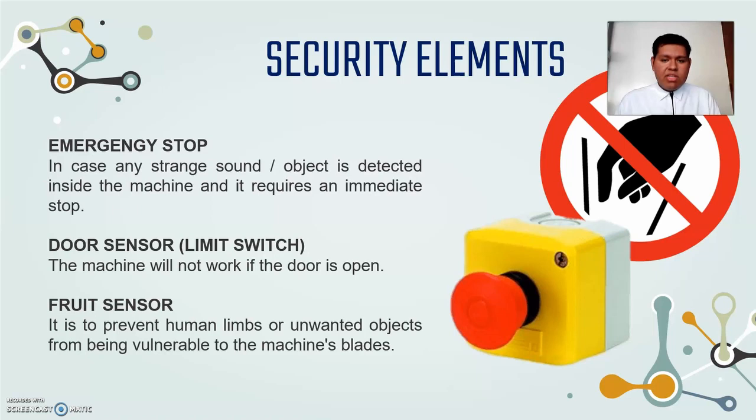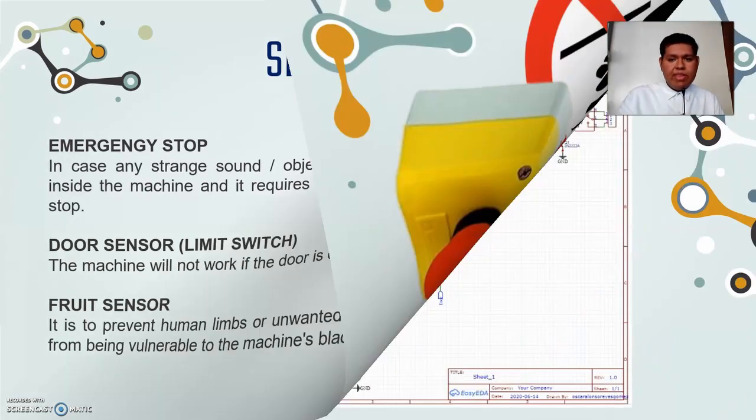Next we have the door sensor, that tells us when the door is on or not, and the machine will not work if the door is open, so that we don't contaminate the product or expose the users to mechanical parts. It also has a fluid sensor that is not only used for the timer function that we implemented, but it also serves as a safety: if it detects something for more than 2 seconds, it knows that something that shouldn't be there is obstructing the pace of the fluid, so it stops the machine if it's required.